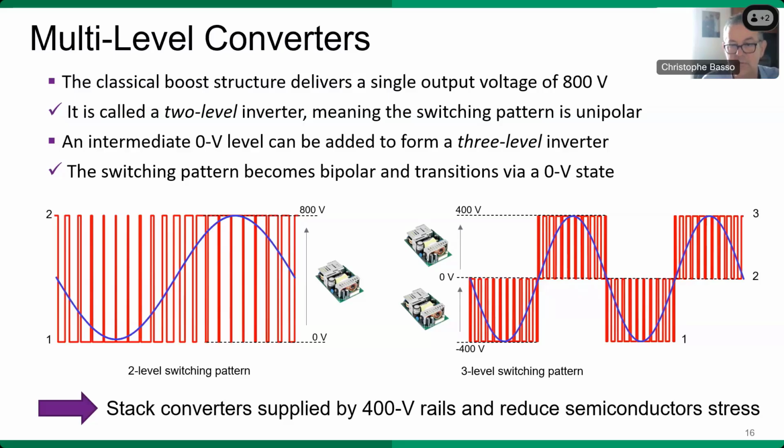So from, let's say, 85 to 150, they set up the DC level at 250 volt, and when they detect that it's going into European mains, then they switch to 385 or 400 volt DC. And then with the two different operating ranges, the efficiency nicely benefits from this dynamic adjustment.